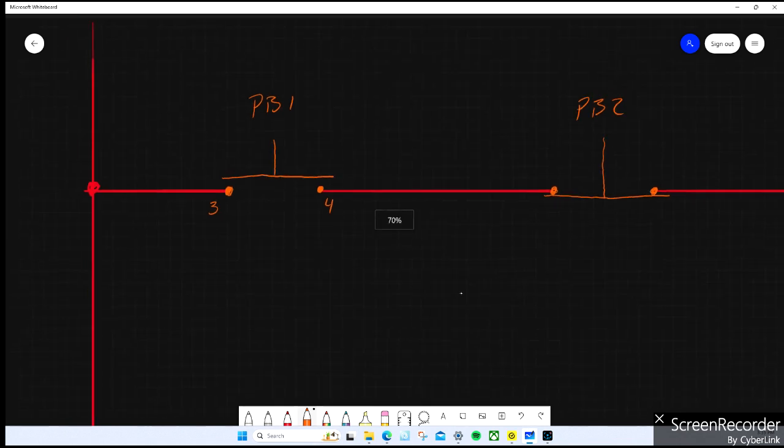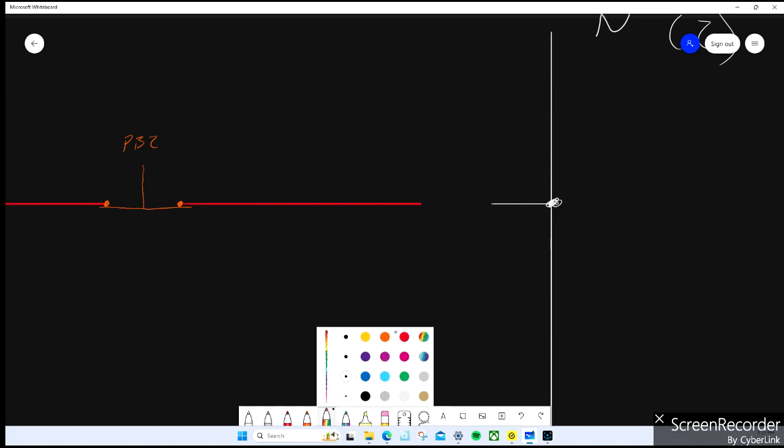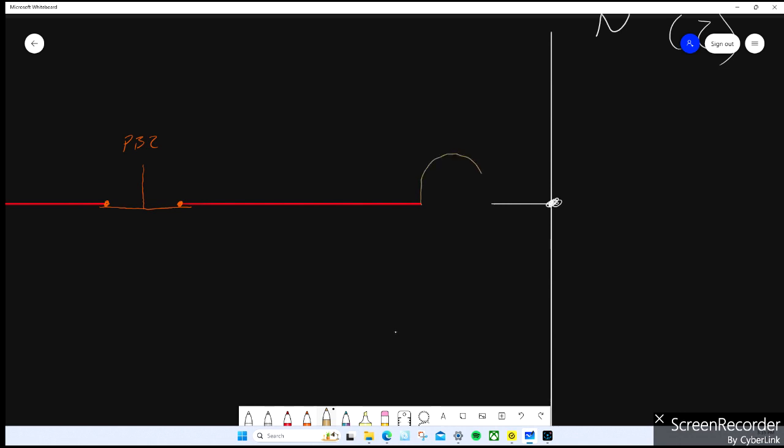And then, because it's a latching circuit, I know I'm going to be using a relay, so I'll put a light in here. I don't know what color we'll make it. Whatever shows up nice. Let's do this color. There's my relay. We'll call it CR1. That could be CR whatever. A lot of times when you get AutoCAD drawings, the relay will represent the line number that it's on. So if I was on page 1, line 1, I'd probably call it CR101. But for simplicity, this is just CR1.